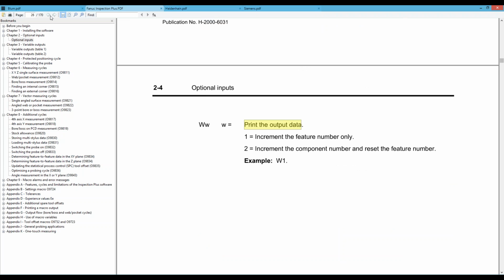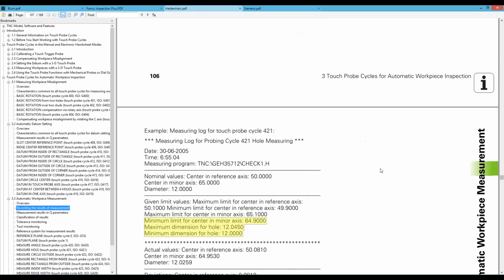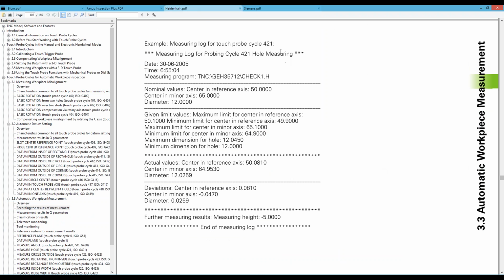Also, with Heidenhain, we can have a report recording like this example. Heidenhain will save a file in the controller. The same with the Fanuc controller. It can save the file on an internal flash drive or send the program through the RS-232 port to the computer and save it on the computer. There are different options, but this is an example of sending a report and checking it later.